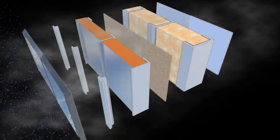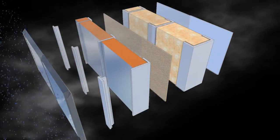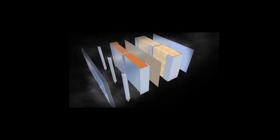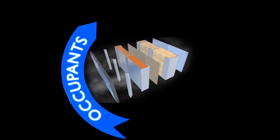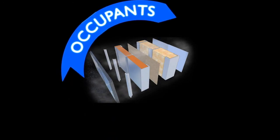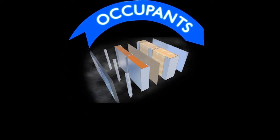In order to avoid the occurrence of excessive condensation, which can result in mould growth and damage to the building fabric and/or contents, designers should assess the amount of water vapour likely to be generated within the building and determine the resultant increase in internal vapour pressure above that of external air.